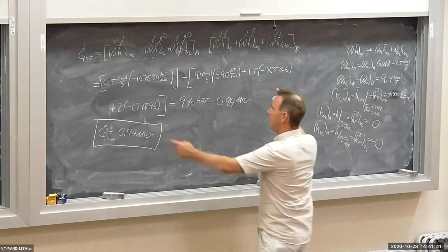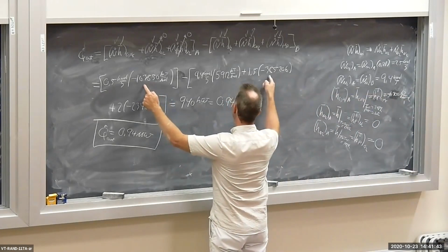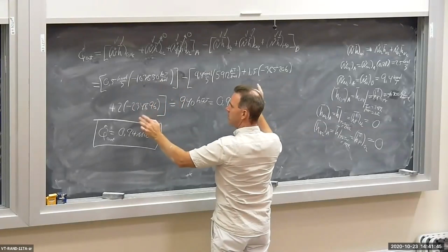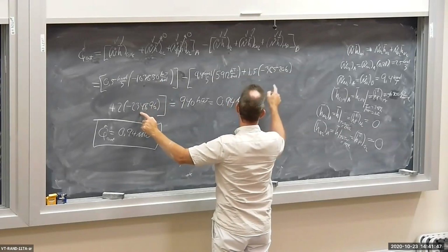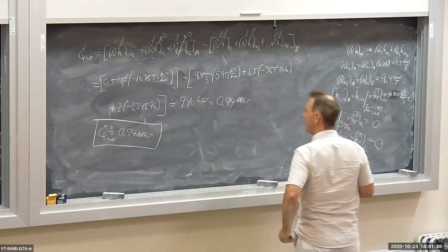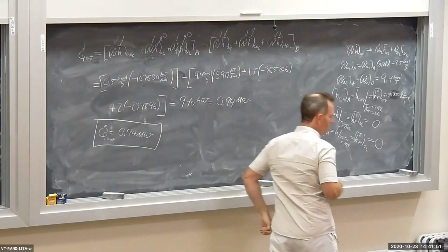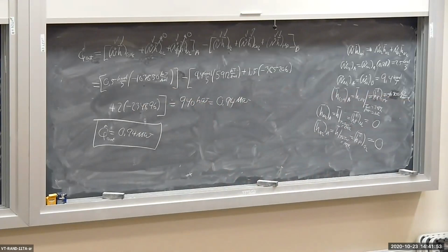The enthalpies of the H2O, the CO2, and the fuel are large numbers. Forget the sign, they're large numbers, and they're large because they have the chemistry included. They have the enthalpy of formation included in the calculation. So Q dot would be completely different and incorrect if you didn't include the enthalpy of formation.